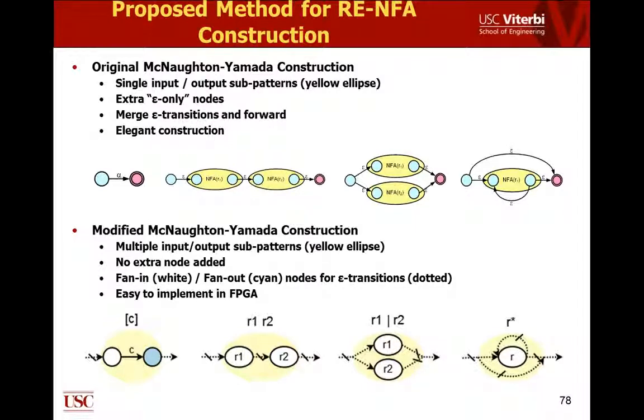So if you have such connections, for example, here I can have something that goes from here. It could have epsilon transitions there also, go one more here, and then go like that. It is possible to have a long chain of epsilon transitions. The problem with this is that if you implement this on FPGAs, if you build a circuit for that, that can result in long connecting wires, meaning that your clock throughput is going to be low in those implementations.